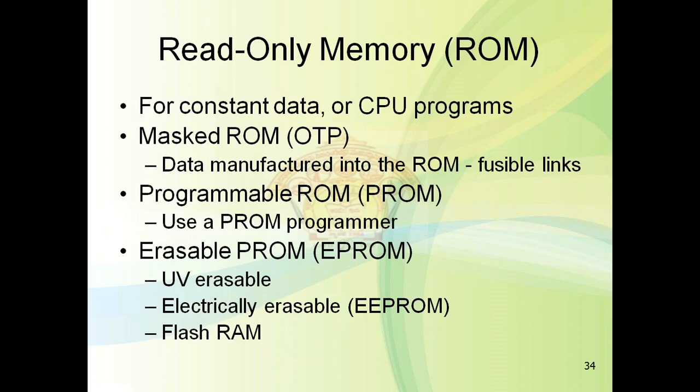There are again different types of programmable ROMs. We can program and write it, but whenever we want to rewrite it, we have to erase it first. Depending upon how we erase, there are different types, first being ultraviolet ray erasing.